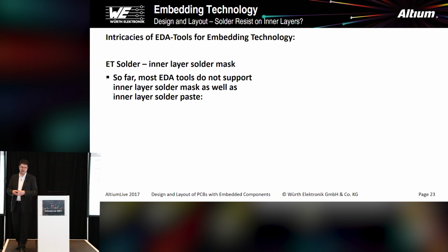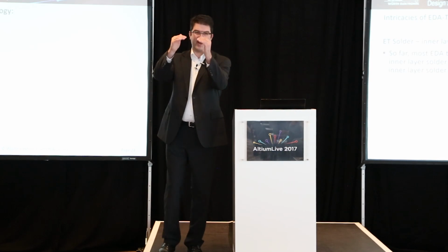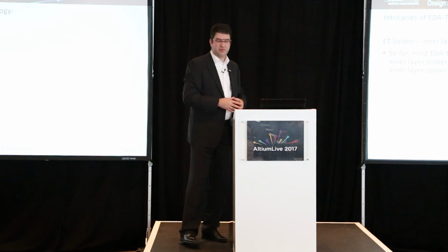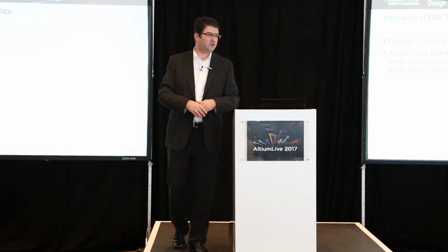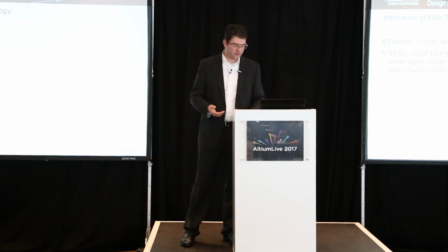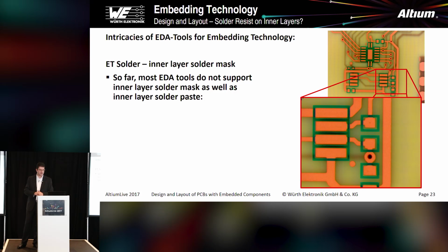So thus far, no EDA tool I know on the market is capable of even creating inner layer solder mask and inner layer solder paste. This would be the next thing I would really like to have Altium offering in the future, so that it's easier to create such boards. At the moment, you have to overcome this by introducing, again, another mechanical layer.